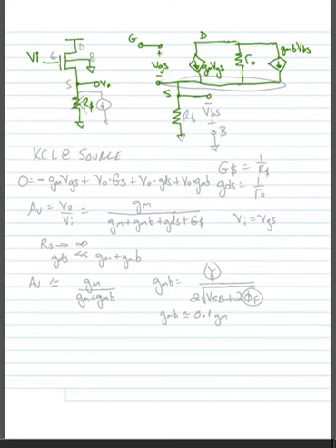We have a resistance here, and we have a bulk terminal now that we see from this figure is grounded. So this difference in voltage between the bulk and source terminal is labeled our bulk to source voltage. Now, if we write KCL at the source node, so we're doing KCL at the source, we find this equation.